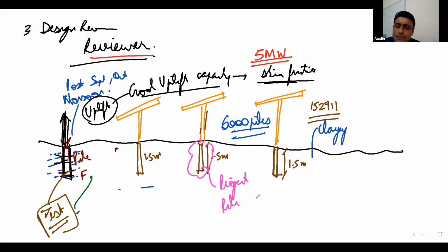I will tell you all these names in the code. These are called routine tests. So this you have to carry out on your project piles. Now they started these routine tests after I think 500 or 600 piles. Out of the total 6,000 piles that were cast, they started doing their routine tests.